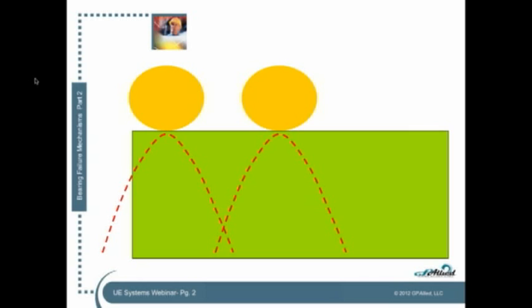So what this means is when there is an inner race defect, like from fatigue or like from contamination, when we collect vibration data or when we look at the ultrasonic data in a spectrum, we're going to have a signal or a peak, and we'll get into this in a little bit, at that frequency at 8.193 times turning speed. So in this particular case, 8.193 times 29.583, that would be our frequency in cycles per second, or hertz, right? So more on that later.